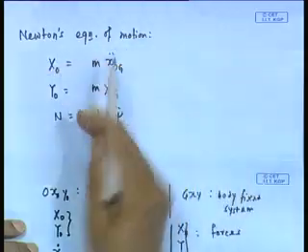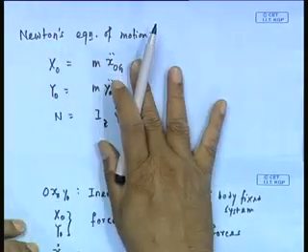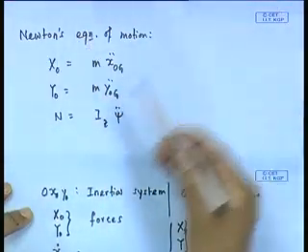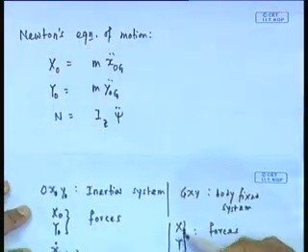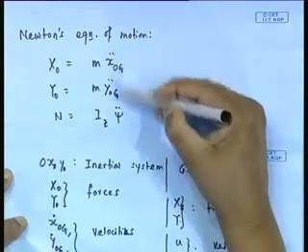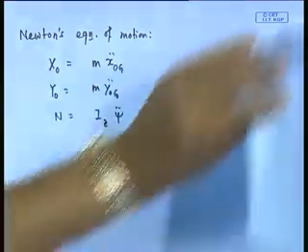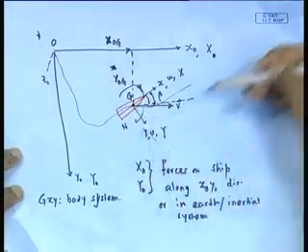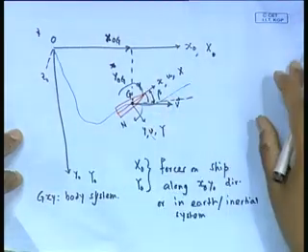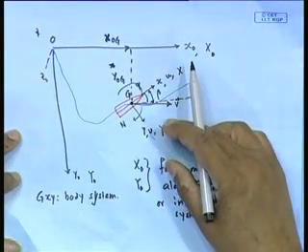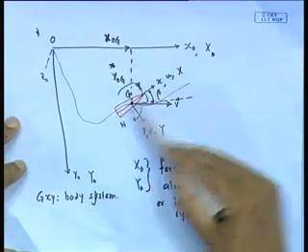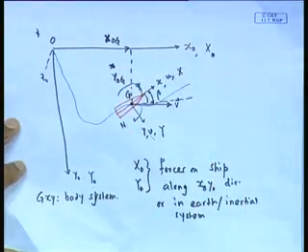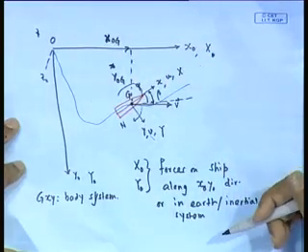This equation, right hand side and left hand side, x0 y0, x0g y0g, that is body inertial reference, but I want to transform that and write them in terms of x and y, and in terms of this side u and v. Why? Because remember, there is a shape here, the red one, and I want to find the force acting on it because of its motion. If you are sitting on the shape, you are much better off trying to determine the forces along its x axis and along its y axis, because along its x axis is a resistance force, along its y axis is a sway force.